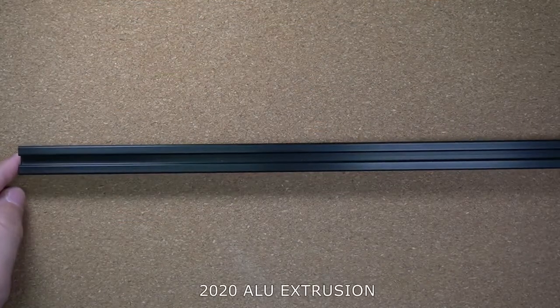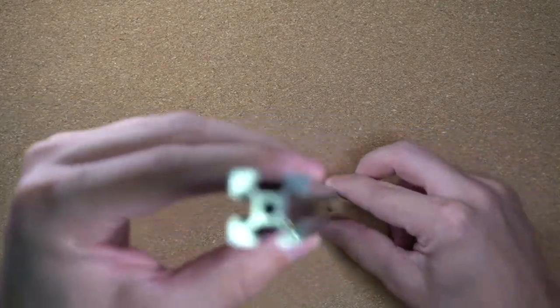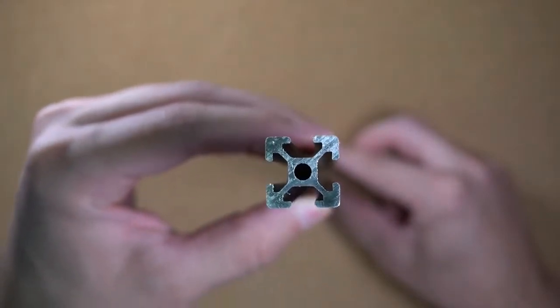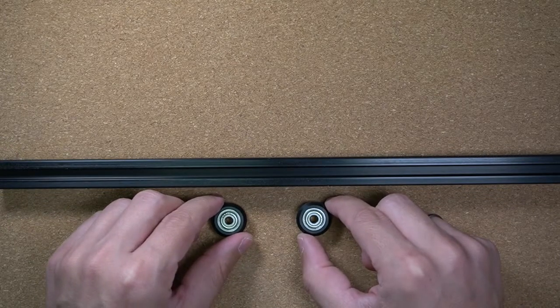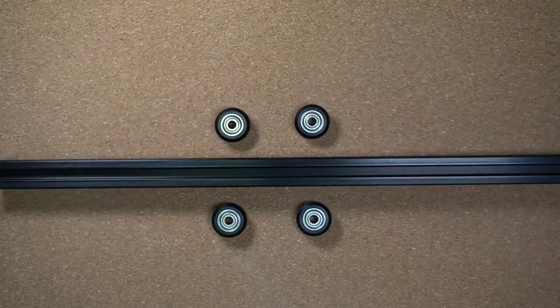For the main body or the frame of our camera slider, we will use a 2020 aluminum extrusion. It is inexpensive, super easy to source, and also you can get it in any length you need. So if you decide that you need a longer or shorter camera slider, you would just change the length of the aluminum extrusion and everything else remains the same. Also, it's going to make our camera slider very sturdy while keeping it very light for carrying around or mounting on a tripod. We will use 4 V-shaped sliding wheels to attach our camera platform and allow it to slide